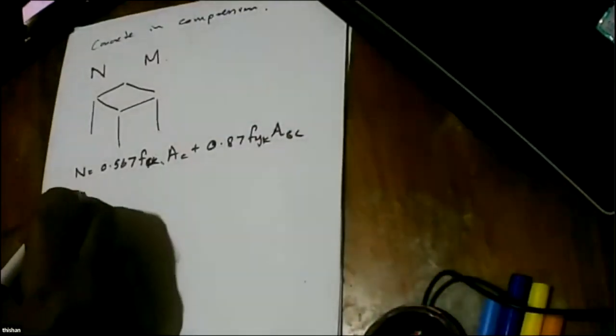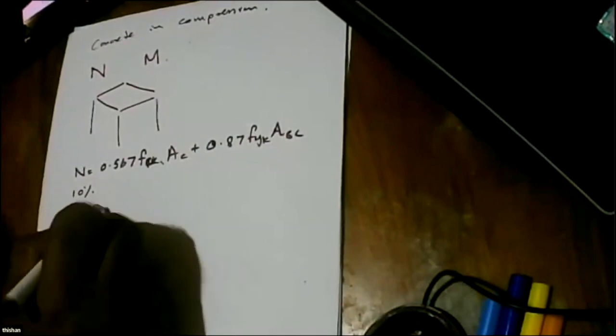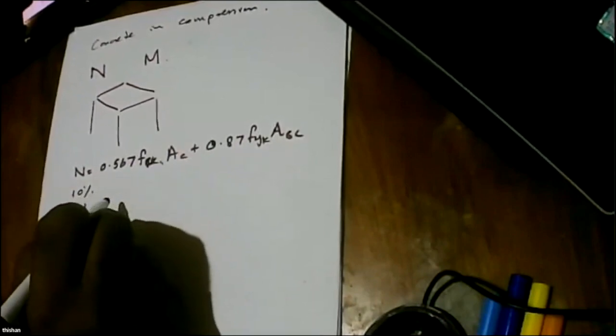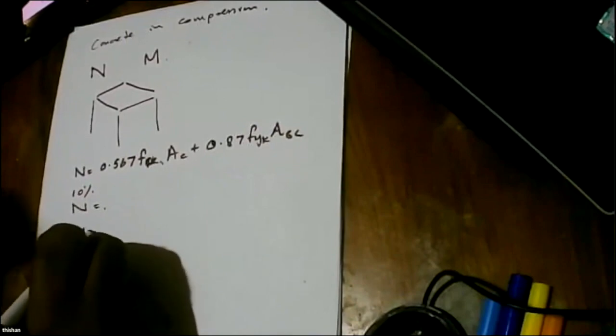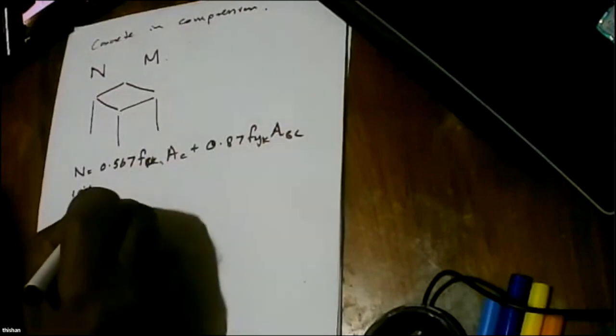And then I said, this is the maximum capacity, so apply a 10% reduction first to design a column subject to axial loads plus small bending moments. But if it is in a structure, we generally again reduce it by 10%.